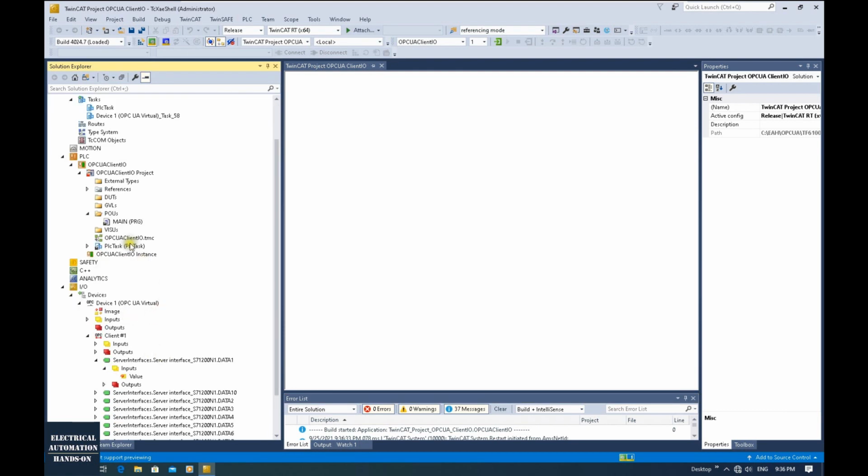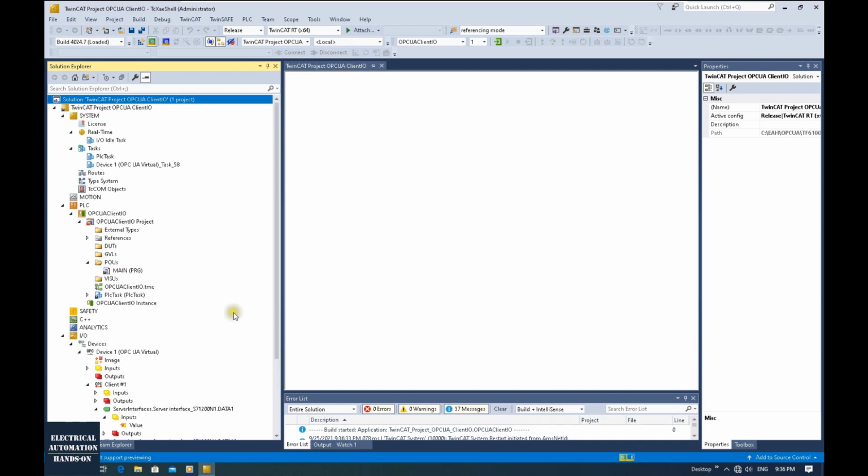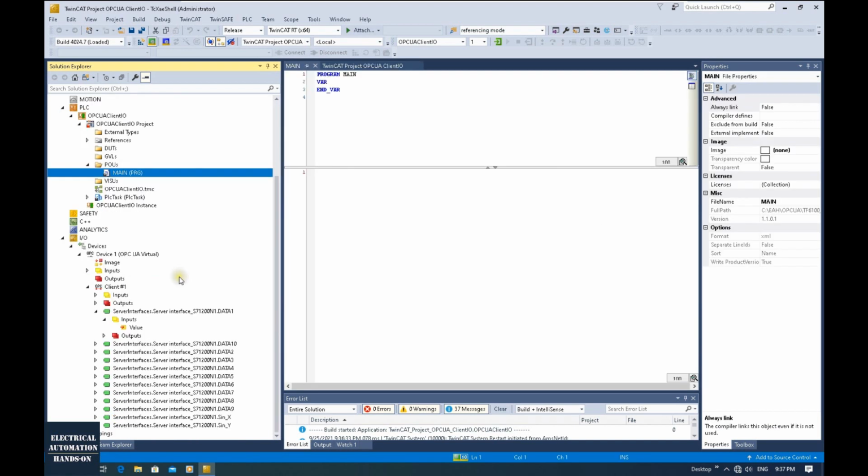That's because while using this OPC UA client, this ClientIO method only needs us to configure this IO configuration, and then link the PLC tag. So we do not need any PLC program to set up the OPC UA connection and send or receive the data. All the data are cyclic. And now to briefly verify if this communication is working, we can go to here.